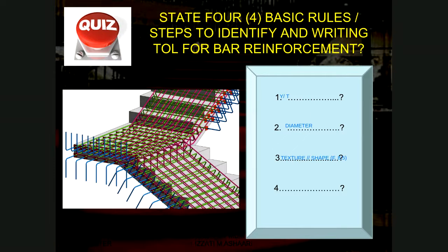But if you look at F.8.4, you have A, B, C until J. So what you have to refer to is F, that is in step, staircase, and the string and associated landing. That means it's under one clause or one category. So this is the summary of how you identify the bar reinforcement taking off list. You identify this, then it will be easier for you to measure.